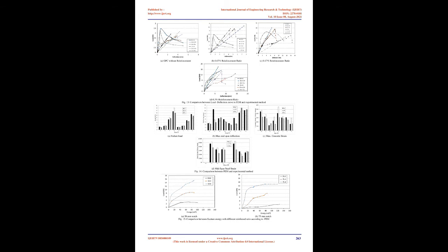Dilation angle is related to the ratio of plastic volume change to plastic shear strain. The eccentricity is a small positive number that defines the rate at which the hyperbolic flow potential approaches its asymptote. The ratio of initial equibiaxial compressive yield stress to initial uniaxial compressive yield stress. Viscosity parameter used for the viscoplastic regularization of the concrete constitutive equations. This parameter is ignored in Abaqus.